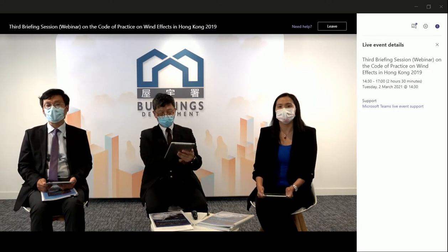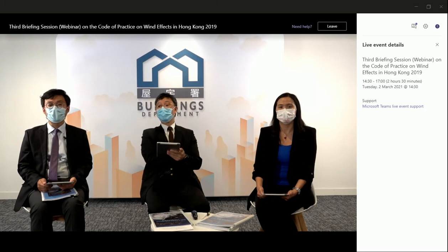The general principle is, for the tower design, especially for the podium design and the foundation design, we need to make sure that we can cover the most critical global translational load case and the global torsional load case. For the global translational load case, within Appendix E, we further explain that the whole plan can be divided into 8 divisions.